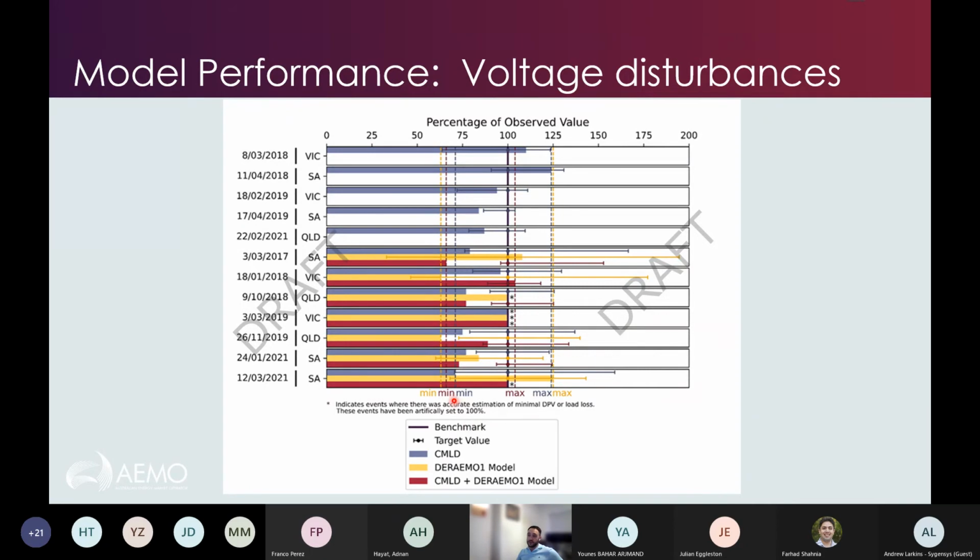They know using these min and maxes that it could be anywhere from 70 to 105% of that estimate based on our results. So that 100 meg could be anywhere from 70 meg operational demand change to 105 meg of operational demand change. And once they know that, they can do things like set contingency sizes accordingly, set FCAS levels accordingly, and I guess overall make the market more efficient.